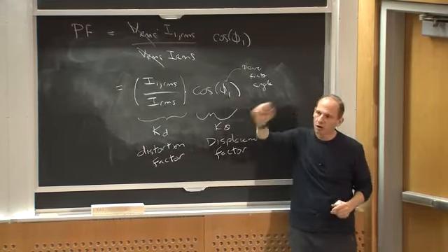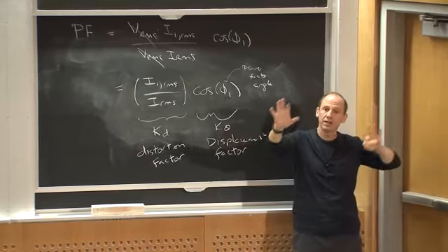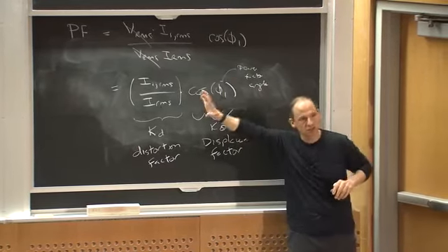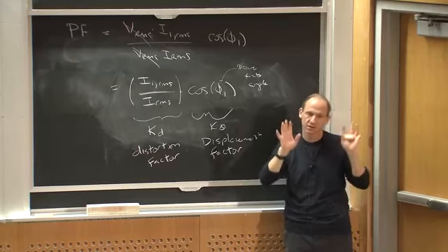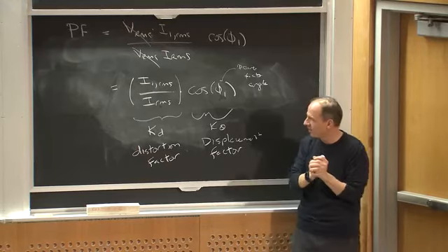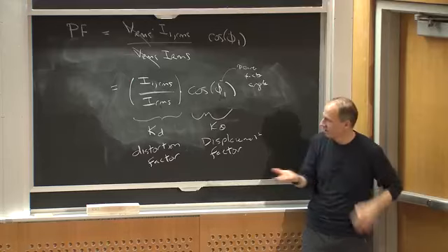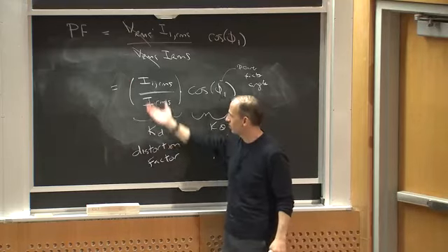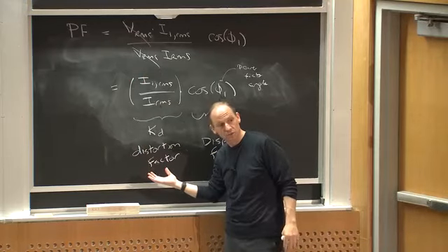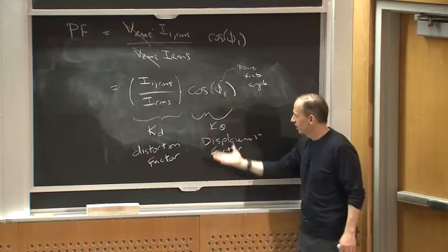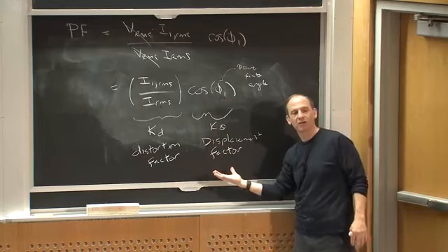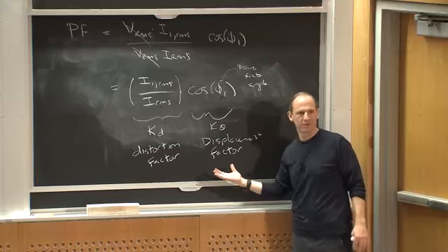So we can hurt our power factor. We can hurt our ability to utilize the source to transfer energy. It's not how much energy we're dissipating, it's how much utilization do we have. I can damage it in 2 ways. I can damage it by drawing a bunch of harmonic current that doesn't deliver power, or by delivering components of current that are out of phase with the voltage, which also doesn't deliver power.